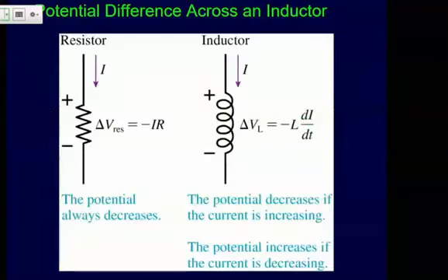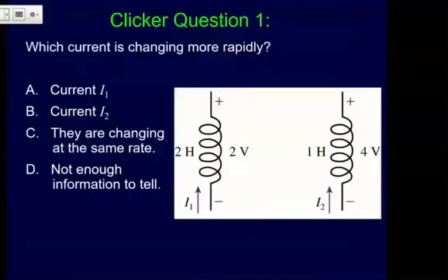And so this is our voltage for the inductor, and this is a little sheet that summarizes that. If you remember, when we did this for resistors, if the current was coming this way, we modeled it this way, which to us meant that when the current came in, the potential decreased. So our potential was decreasing through here. It's the same idea in this case. We got this negative sign, and so if di is positive, then this will be a decrease, which means the EMF is pushing the other way. And if this is negative, those signs switch. So that can be a handy thing.